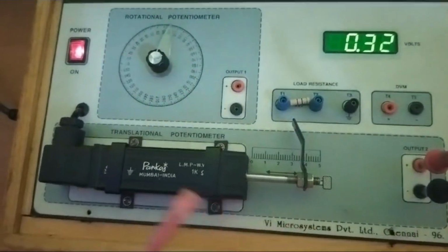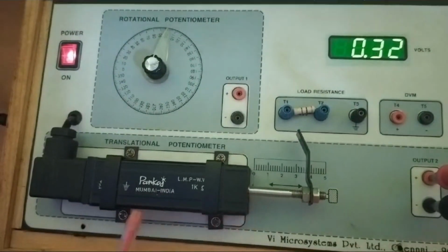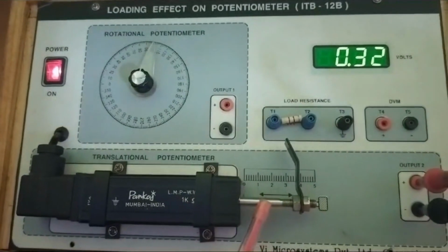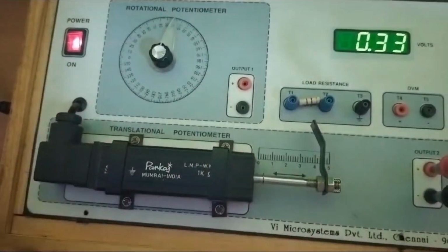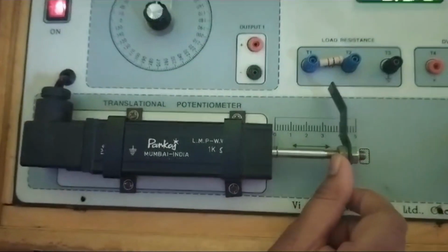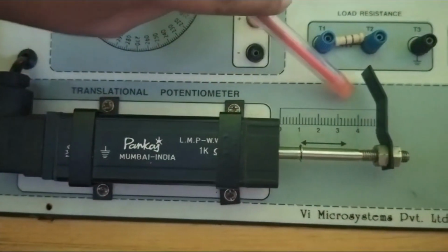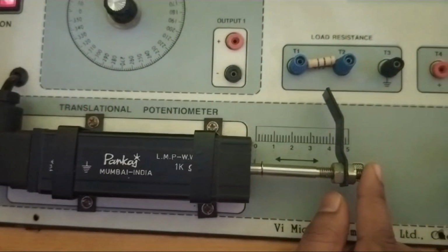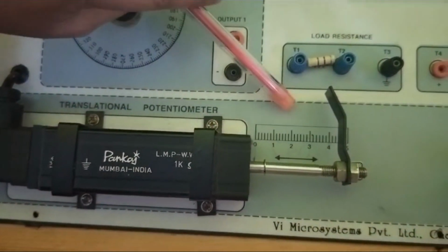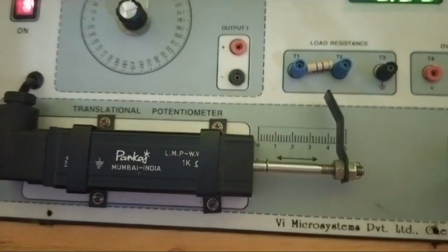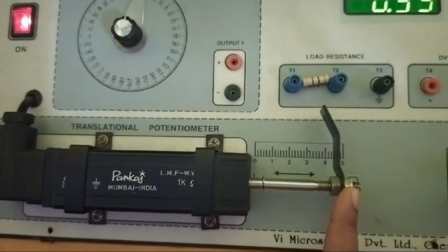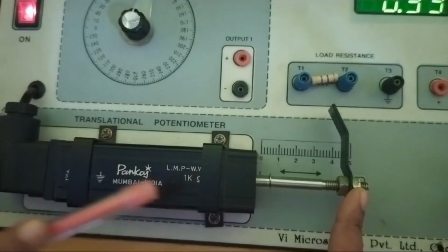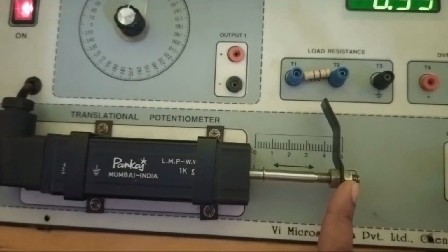So this is the basic construction of my potentiometer. Inside, we have a resistance, and this resistance can be varied with the help of the shaft. This movable part is called the shaft of the potentiometer. Along this shaft you can find a linear scale arrangement in parallel. Whenever I move this shaft, according to the shaft displacement, I can observe my displacement readings at the top end. Whenever the displacement is given with the help of this shaft, inside this specific area the resistance is varied. The change in resistance is converted into the output voltage.